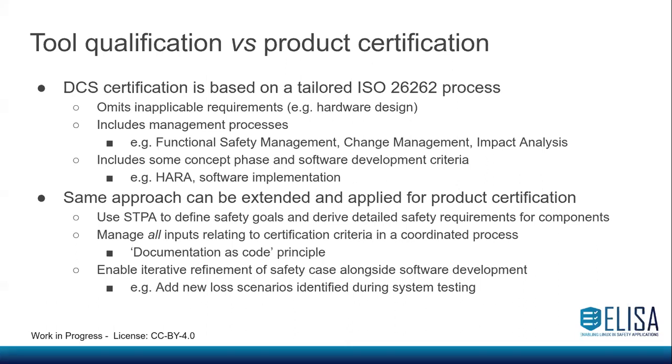But fundamentally, it also illustrates how you can iteratively refine a safety case alongside software development, which at first sight may seem to go against the principles, the V model principles that you see in standards like ISO 26262, but it doesn't really. I think that the V model isn't about a single flow waterfall. It's not you go down this side and then you go up the other side once. You do that iteratively. You repeat and you refine, and being able to manage both the safety requirements and the analysis that's going into that, and the software implementation and the verification that you do, all in a coordinated process, is fundamental to be able to implement that kind of model.